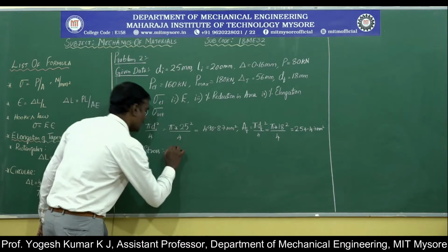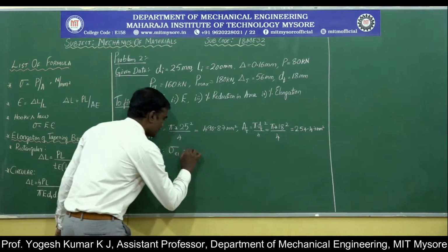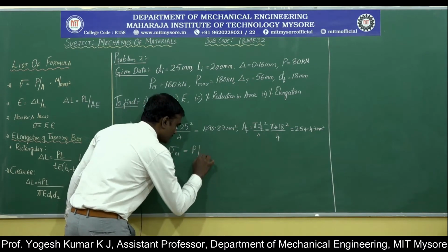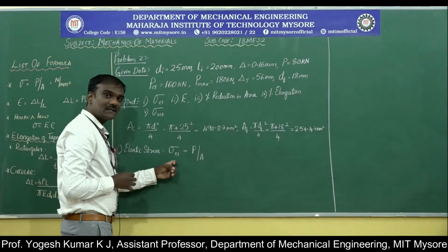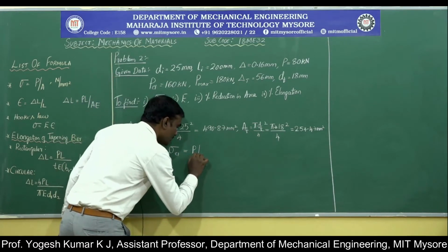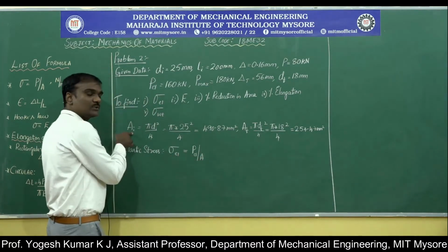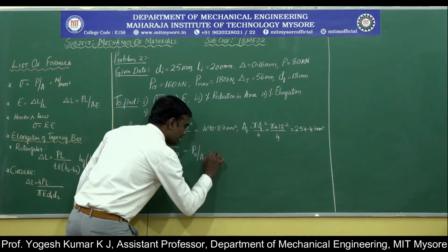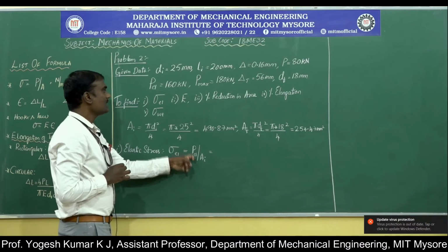So, we will denote that with sigma E suffix L. So what is stress? Force by area. So if it is stress at elastic limit, what load should I consider? It is the load at elastic limit. And what area should I consider? It should be the initial area. So do we know the load at elastic limit?